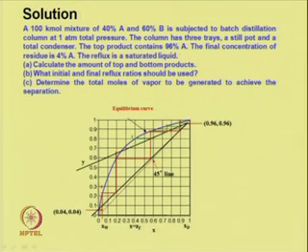There are two operating lines shown over here. We start at 0.96 and draw the 4 stages, and we can obtain x_W with 4 stages as 0.4, and we can calculate the slope of this operating line. The slope also we can calculate for this one over here.